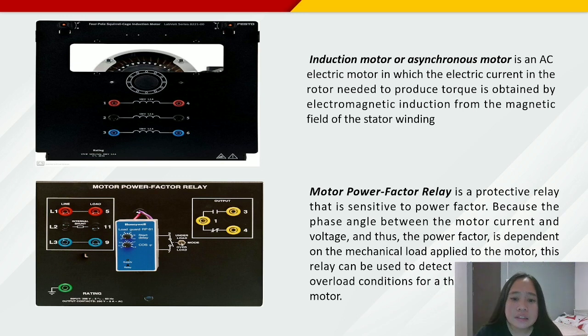On the other hand, a motor power factor relay is a protective relay that is sensitive to power factor, because the phase angle between the motor current and voltage, and thus the power factor, is dependent on the mechanical load applied to the motor. This relay can be used to detect either underload or overload conditions for a three-phase induction motor.